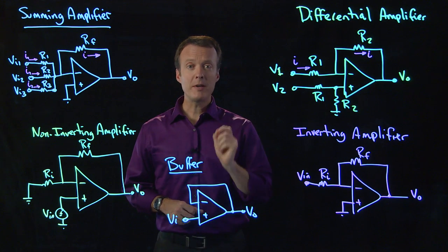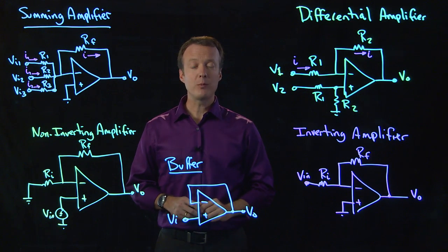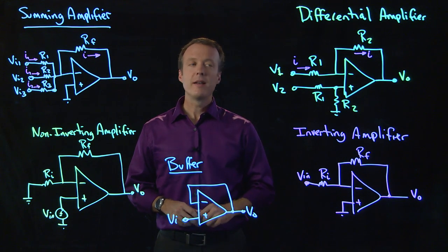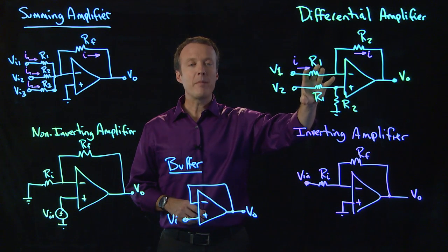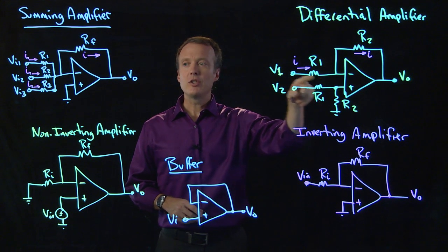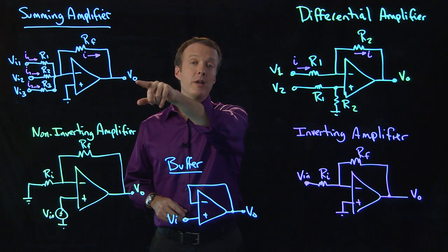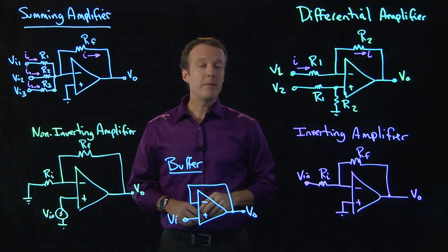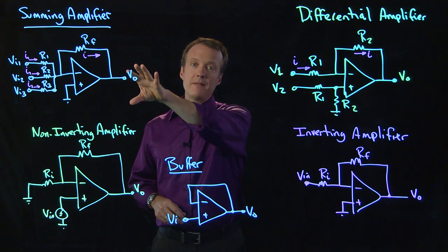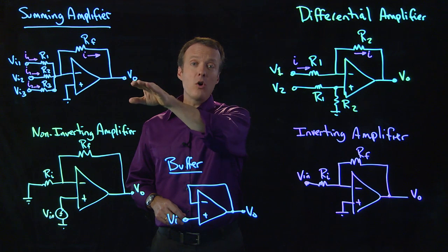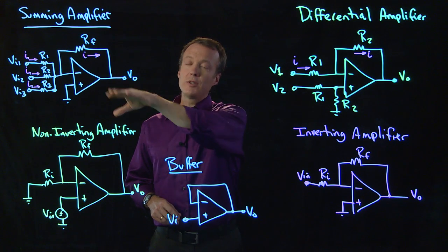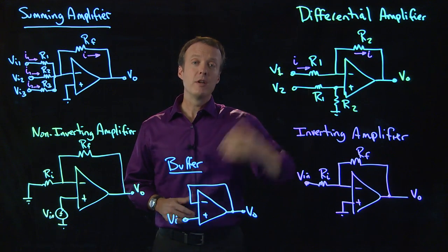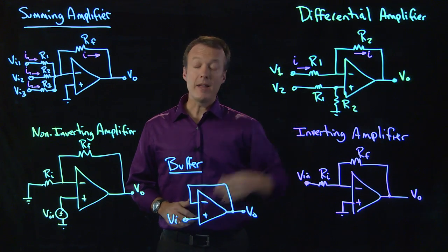First of all, you want to make sure you don't break the fundamental principles we talked about earlier in this module. And second, you want to ensure that the input impedance of one op-amp is sufficiently large so that it doesn't load the output of the circuit that you're connecting it to, such as shown here. The other thing you want to make sure is that the output impedance of the op-amp is sufficiently low so that the entire voltage that the op-amp, or the circuit, is producing will indeed get delivered to the circuit at the output of that.